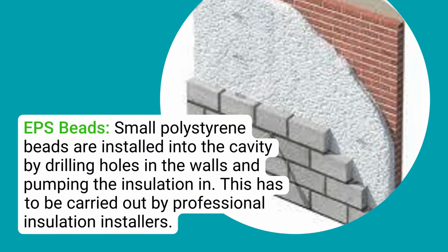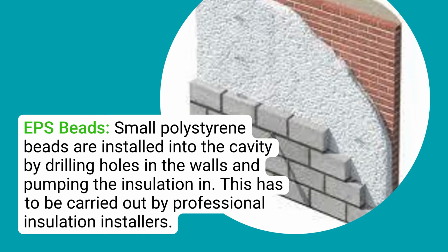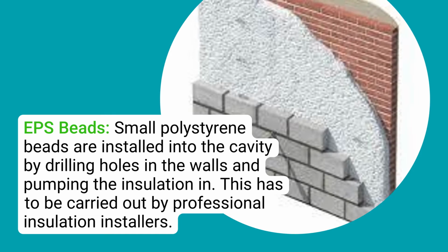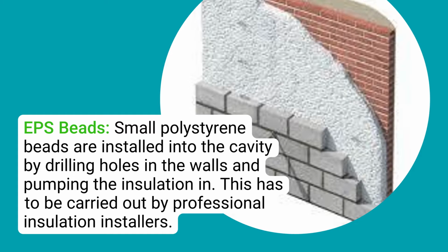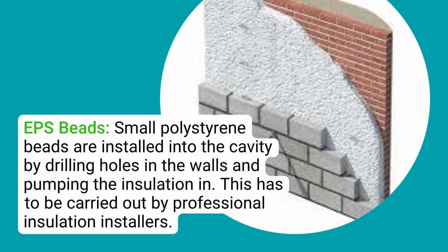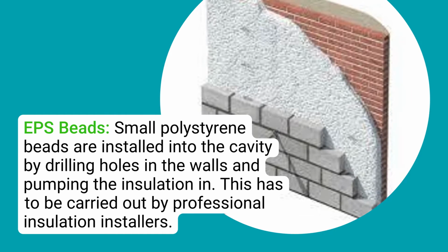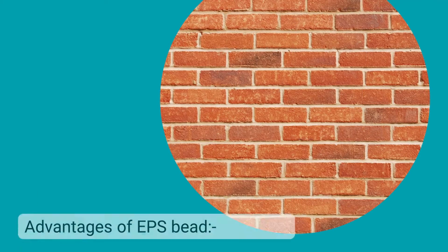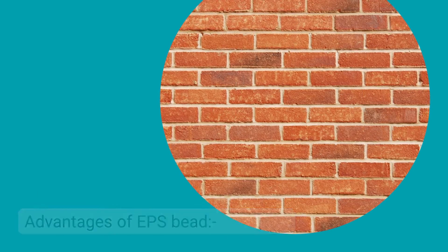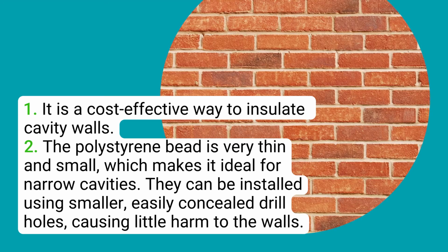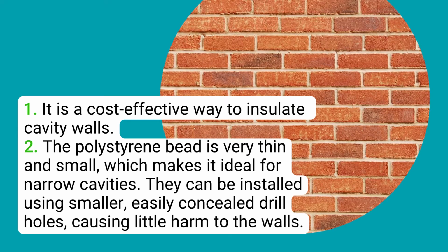EPS beads. Small polystyrene beads are installed into the cavity by drilling holes in the walls and pumping the insulation in. This has to be carried out by professional insulation installers. Advantages of EPS bead. 1. It is a cost-effective way to insulate cavity walls.